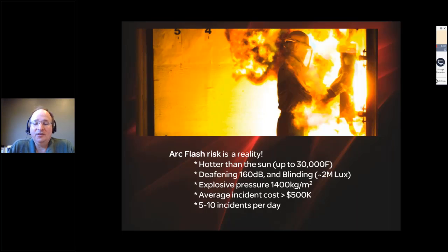I've given depositions now or advice in 17 legal cases relating to arc flash events, and I do believe that arc flash mitigation with arc flash relays and arc quenching and the technologies we're presenting to you today aren't just good ideas, aren't just nice to haves. It's something that ethically, as engineers, we should be incorporating into every electrical distribution system that has an arc flash incident energy over 1.2 calories per centimeter squared at the IEEE 1584 working distance.